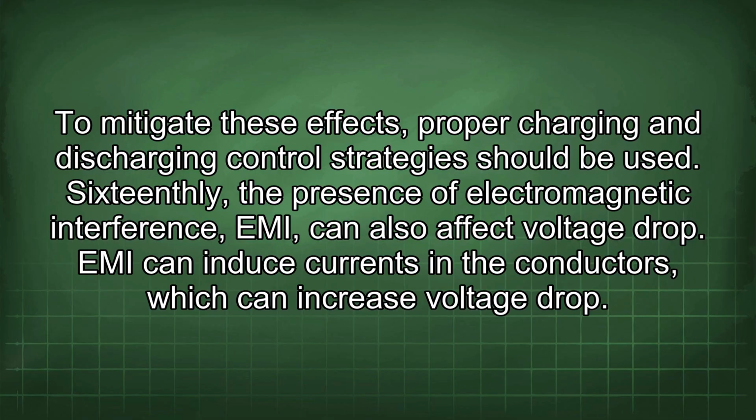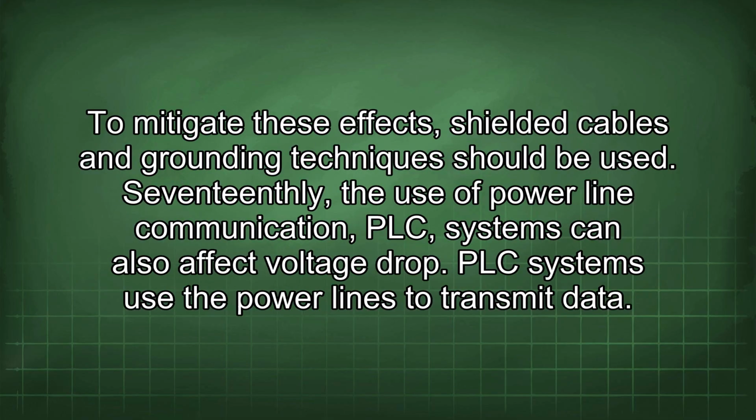16thly, the presence of electromagnetic interference, EMI, can also affect voltage drop. EMI can induce currents in the conductors, which can increase voltage drop. To mitigate these effects, shielded cables and grounding techniques should be used.